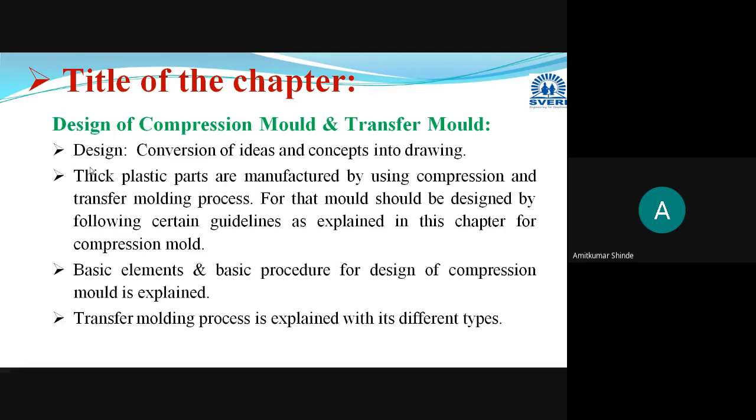As far as the design of plastic parts is concerned, for thin plastic parts you can go for injection molding, extrusion molding, or blow molding, as a number of processes are there. But whenever you want to design or manufacture thick plastic parts, then you have to go for compression molding or transfer molding.